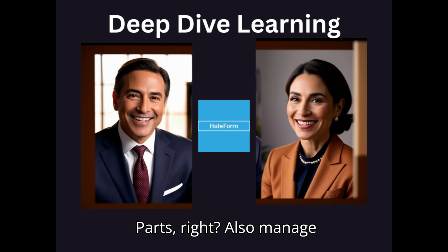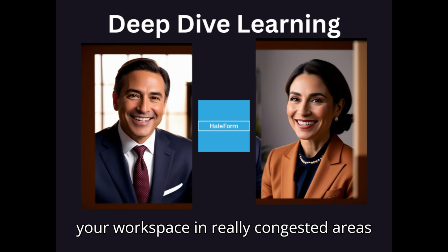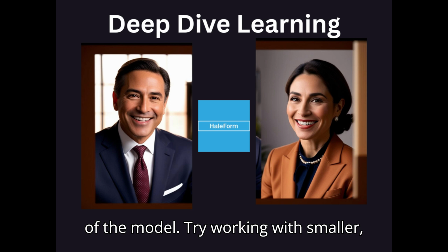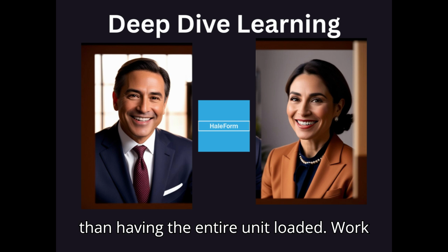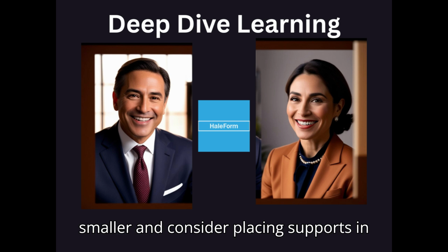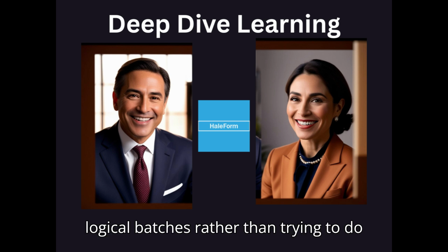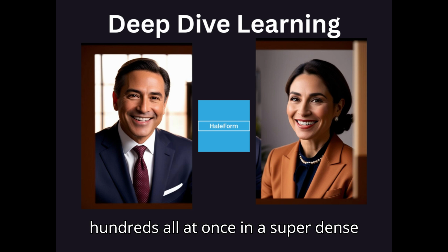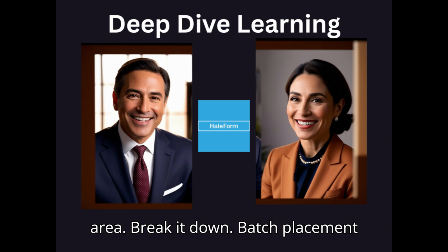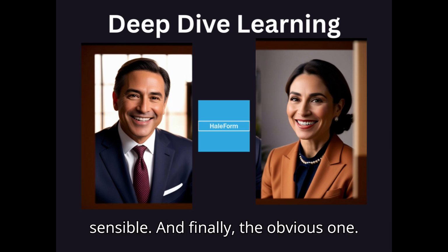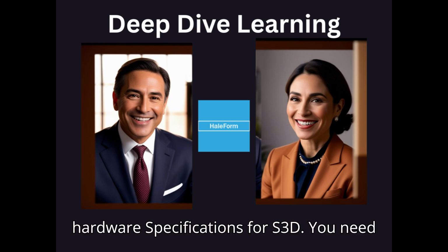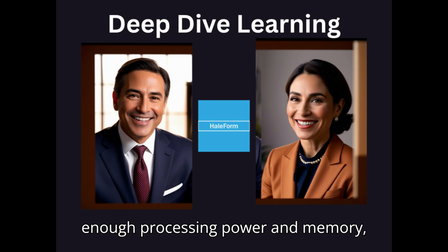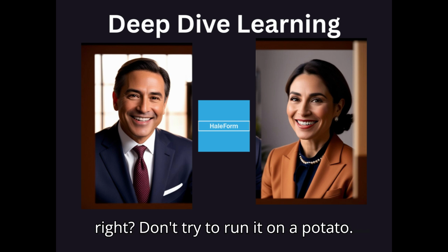Right. Also, manage your workspace. In really congested areas of the model, try working with smaller, more focused views or workspaces rather than having the entire unit loaded. Work smaller. And consider placing supports in logical batches rather than trying to do hundreds all at once in a super dense area. Break it down. Batch placement. Sensible. And finally, the obvious one. Make sure your workstation actually meets or exceeds the recommended hardware specifications for S3D. You need enough processing power and memory. Right. Don't try to run it on a potato.